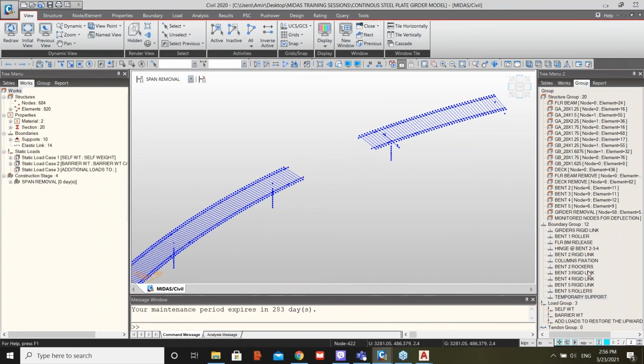In order to do so, there were two techniques adopted in this project. One of them was not only supporting those points with the shoring towers, but rather having jacks installed on top of the shoring towers that can jack against the girders. This way we are pushing up to make sure those points go down until they get leveled together. And the other technique, besides jacking up, was to apply additional loads or additional weights.